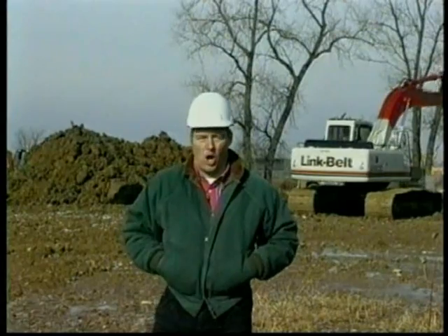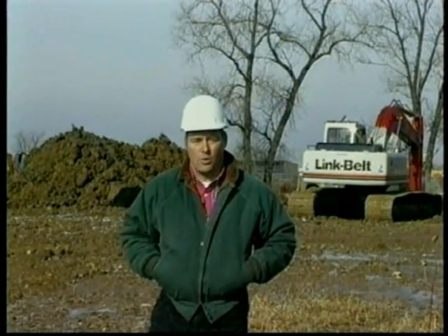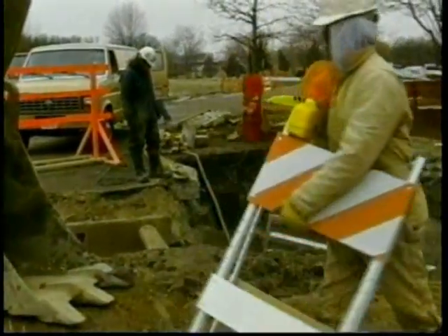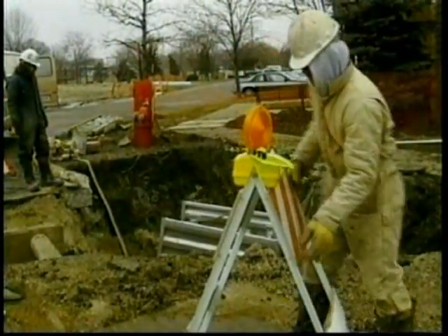To protect employees and public pedestrians, the employer needs to provide for fall protection. That means putting up guardrails on ramps over excavations. And many excavations should be guarded with barricades or fencing to keep out children and the unsuspecting public.